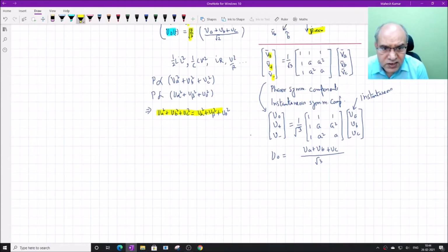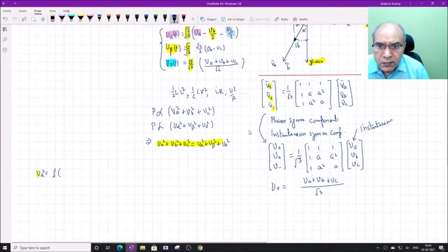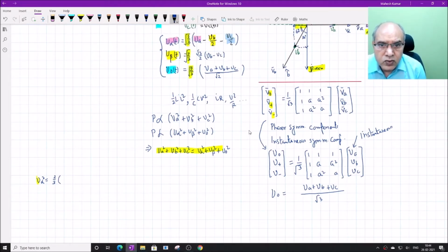Okay. So what is B alpha? What is B alpha square now? I'll put it here. So B alpha square is nothing but 2 by 3 here, and the square of Ba minus Bb by 2 minus Bc by 2, which is Ba square plus Bb square by 2 plus Bc square by 2 by 4, not 2, because this is square, so this is not multiplication.